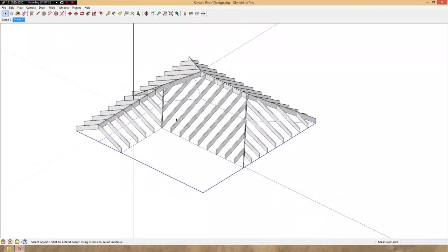It's time for some house cleaning. Right now we have a whole mess of rafters and jacks and skeleton members that aren't named and are not grouped, so it's best to go ahead and name each one of these elements individually, so that later when you spread out these rafters and develop a cut list, you'll have each one identified so that you know how to cut it and where to place it later on.